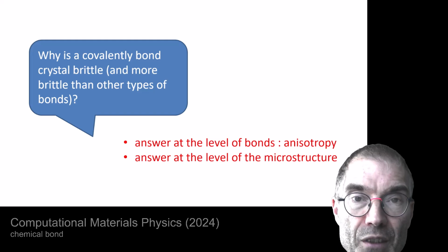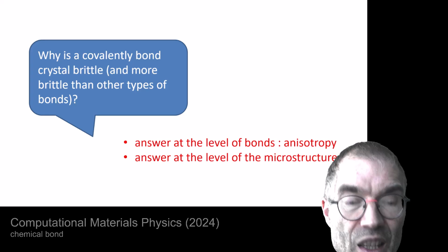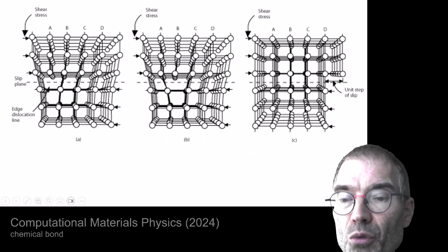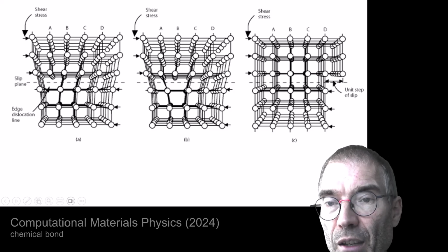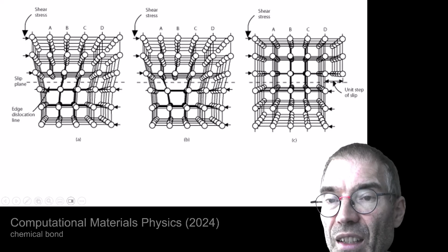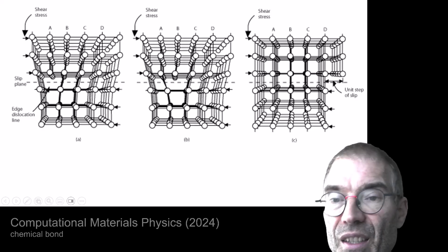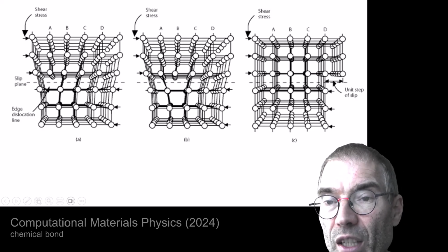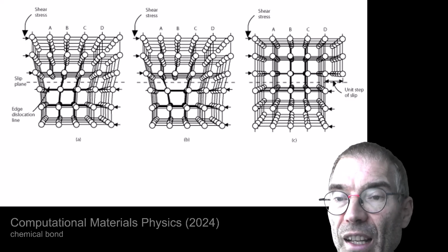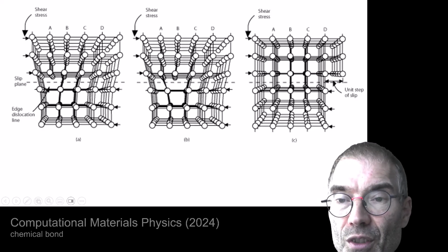You can have defects in a crystal, for instance, dislocations. This here is a cartoon of a dislocation. You have a cubic crystal lattice, and here at the top left, an extra half plane is inserted. So without this plane, this would be a perfect three-dimensional cubic lattice, but half of an infinite plane is inserted.